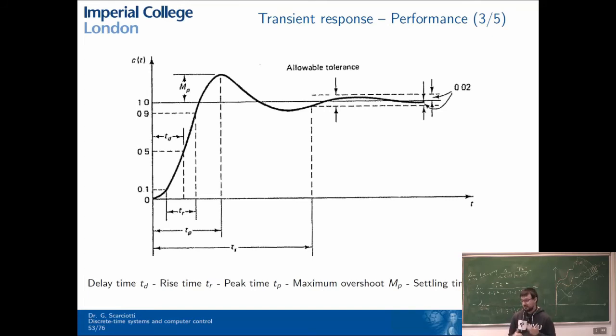And the settling time is telling you when you finally reach steady state. So it's possible to produce a control system that achieves specific rise time, maximum overshoot, and maximum settling times following some specific techniques. For instance, doing control in frequency, as we will see, allows us to set these properties, in particular the maximum overshoot. The settling time instead is mostly decided by the sampling time. So the sampling time of our discrete time system has an important role in deciding the settling time in discrete time, okay?